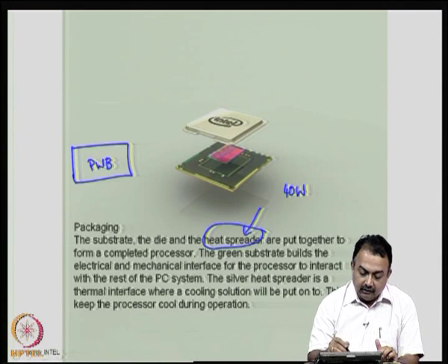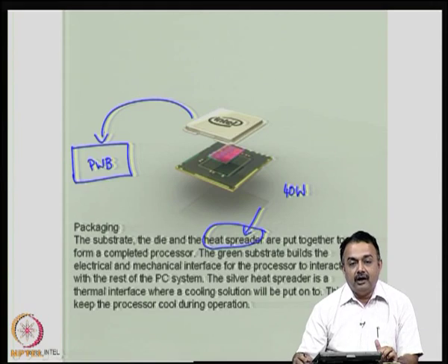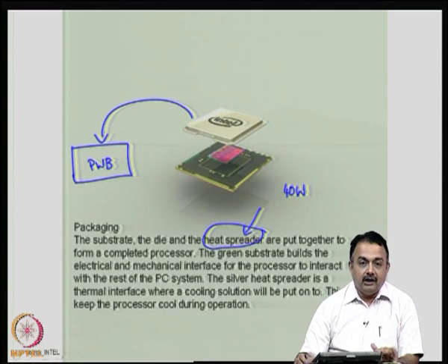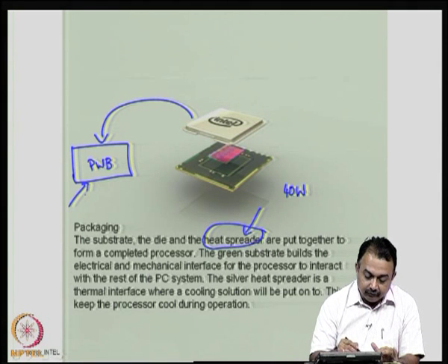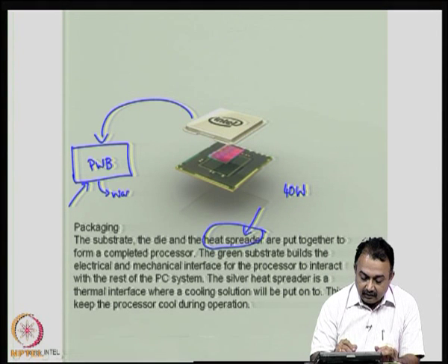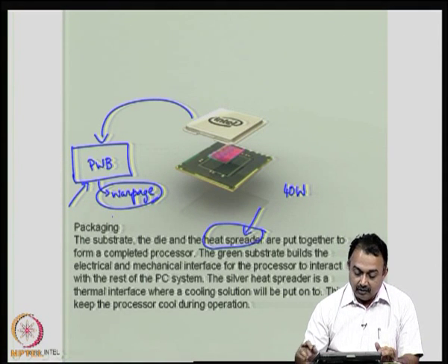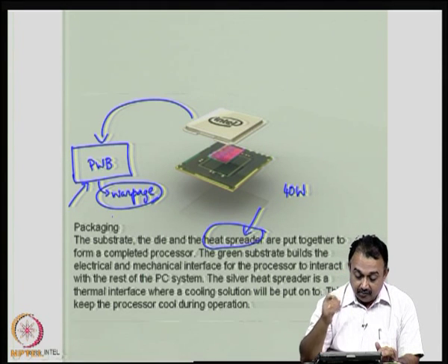Now, the processor will go onto the board and it is interconnected with passives, electromechanical components and so on, and it can be a high dense printed wiring board. Therefore, the presence of a heat spreader on the package is an added advantage, because it will provide a lot of relief to the printed wiring board. Otherwise, the printed wiring board can experience warpage. So, it can have physical damages because of heat not being able to be spread quickly to the ambient.